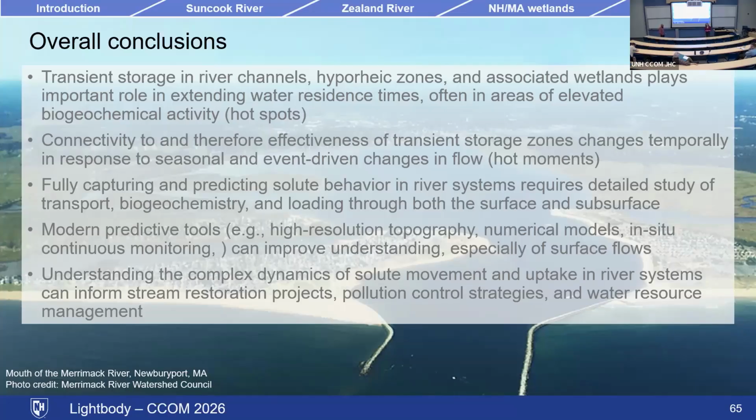Like imagine you had a pollutant that was going down there for days and days. Would that make the tail, once you cease the pollution, last much longer? Theoretically, if you integrate the slug release, you get the cumulative distribution, which is the breakthrough of a continuous release or a plateau addition. If you're really interested in the tails, those plateau additions are used more frequently because they do a better job of capturing that very long tail.